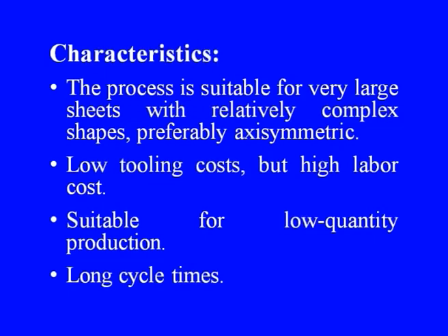Now, let us see the common characteristics of this process. The process is suitable for very large sheets with relatively complex shapes, preferably axisymmetric parts, with low tooling costs but high labor costs, suitable for low quantity production, with long cycle times.